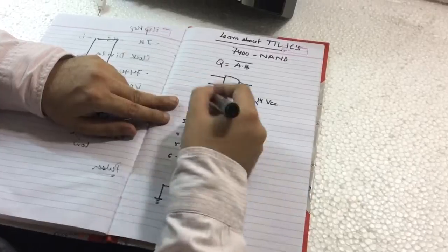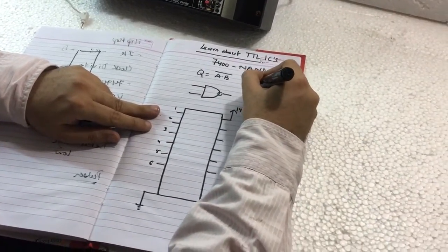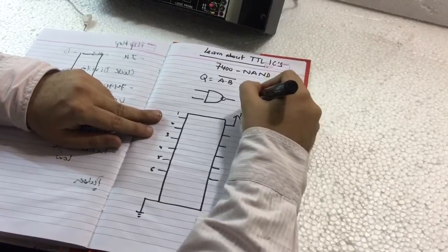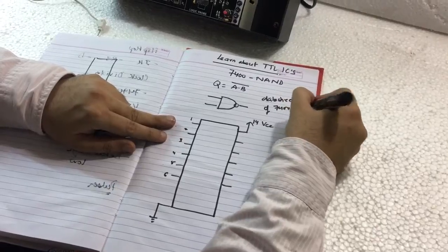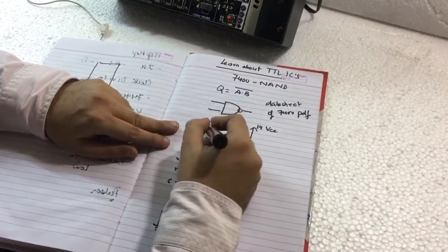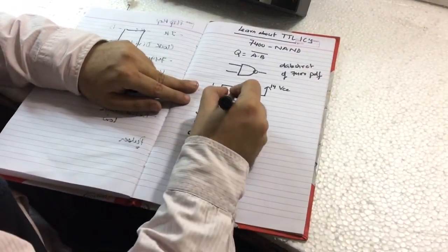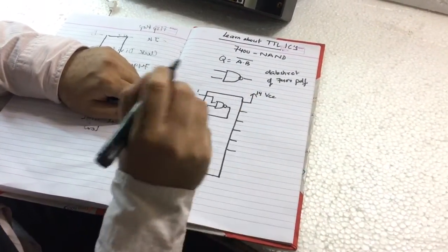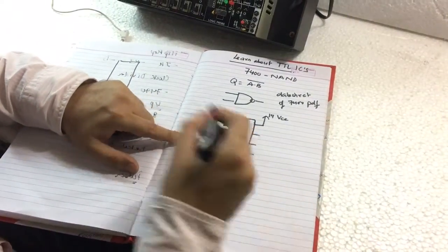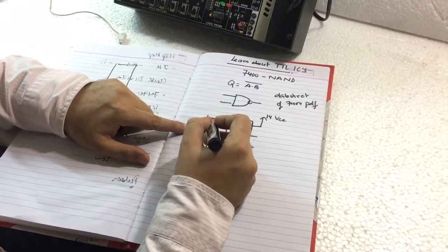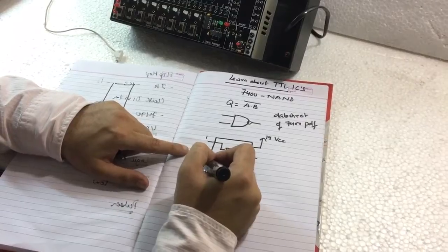For this, search on the internet, Google for the data sheet of 7400 PDF. You will get the full data sheet with the internal connections. I will show you by giving an example of a single gate. There are 4 NAND gates in a 7400 IC. Internally, pins 1 and 2 are connected to one of the NAND gates and 3 is the output.